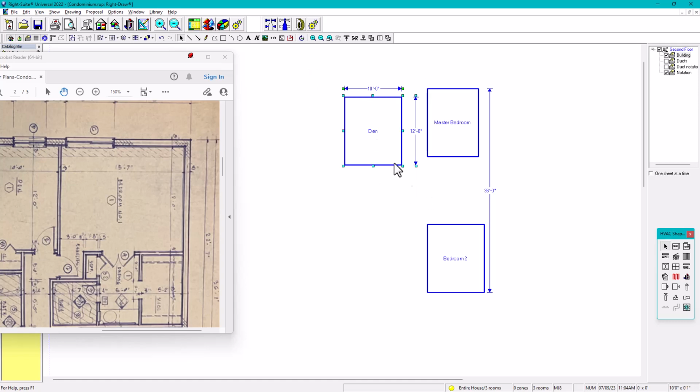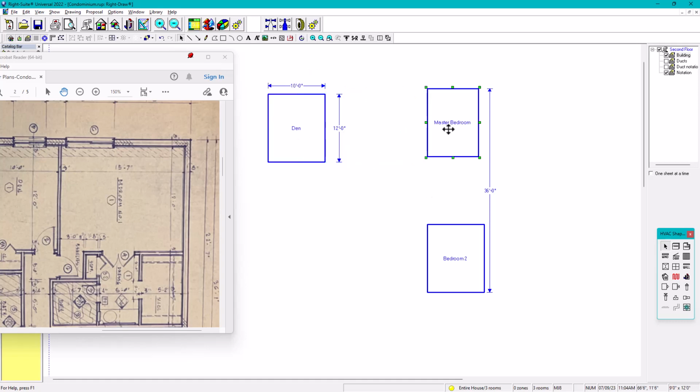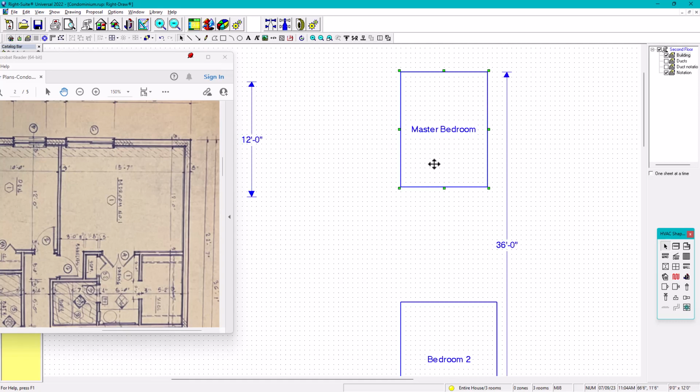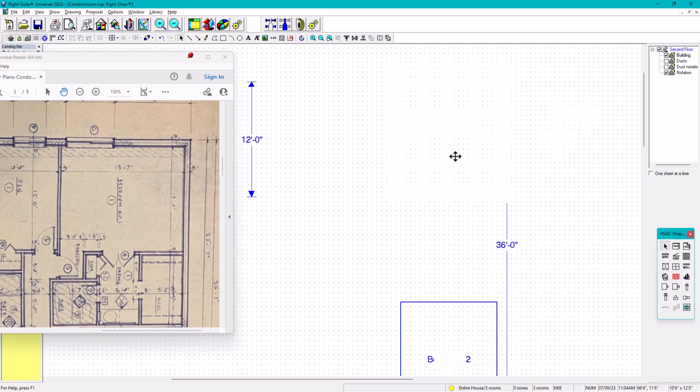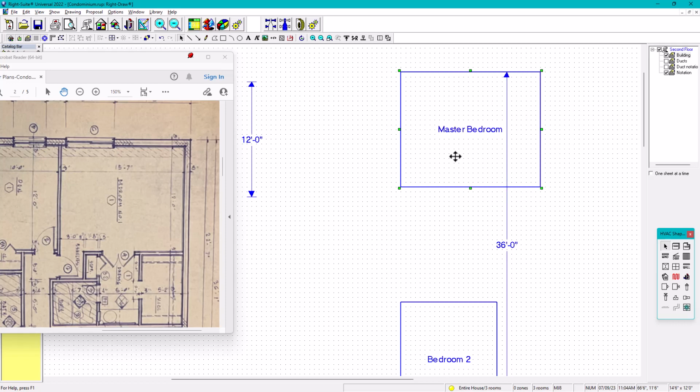So we're gonna move this to the side, so we need more space. Okay, so you can see the dimension right here at the lower right side corner. We have 9 feet by 12 inches. So what we're gonna do is that has to be 15. That's gonna be 15 feet 6 inches, but we're gonna make it 16 feet 6 inches, to account for the exterior wall.